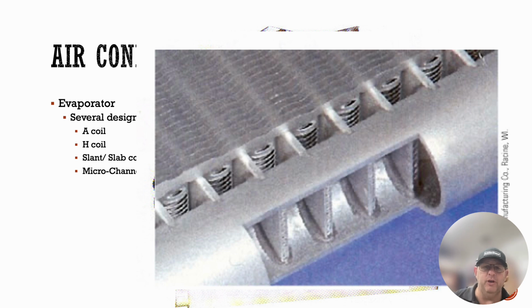And the last one that we're going to be looking at, we're going to be coming out with a lot of aluminum coils. I haven't seen many microchannel coils in our evaporators yet, but I believe that they are coming. And by the time this video is out, you will see those microchannels in our evaporators. They just increase the surface area of that particular unit very well, so that we'll be able to lessen the amount of room that our evaporators are going to have to take up within our units themselves.